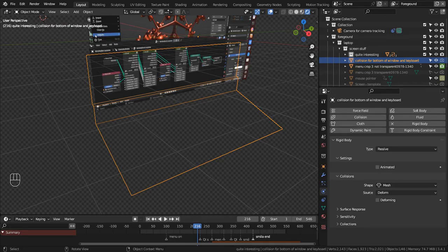Next, I added this simple non-rendered mesh against which all the animated nodes will collide and which simulates the laptop screen and where the bottom of the geometry nodes editor is and where the laptop's keyboard is. To keep this project a bit simpler, I kept the simulated laptop screen vertical and used a photo of my laptop from the side, imported as a plane, to angle the simulated laptop keyboard. This means that the initial positions of animated nodes, etc. could be set in orthographic right view, and X was simply how far in front of the screen objects were.